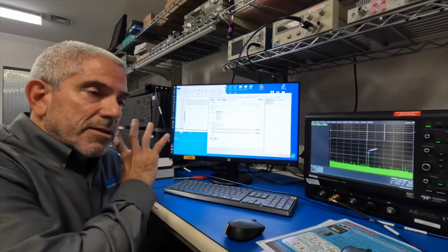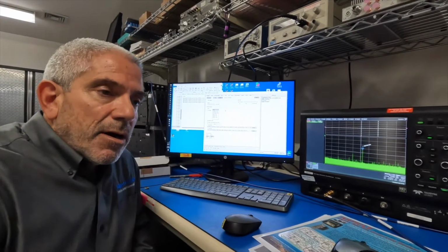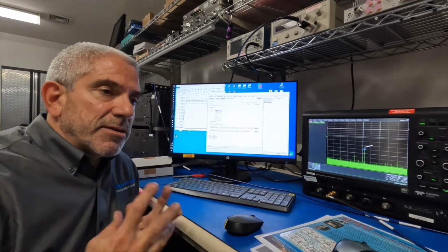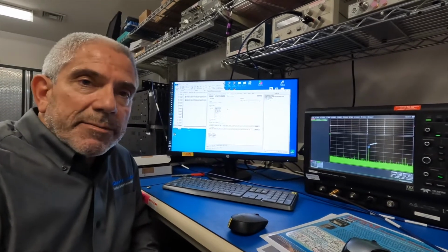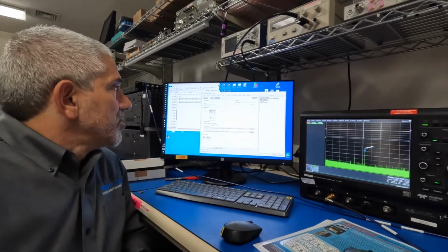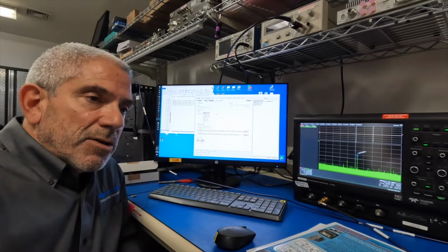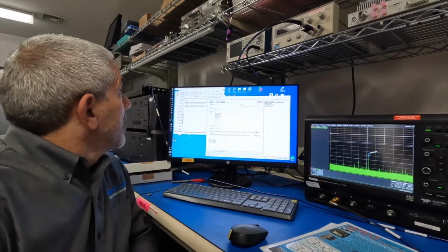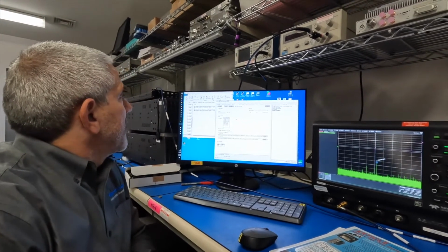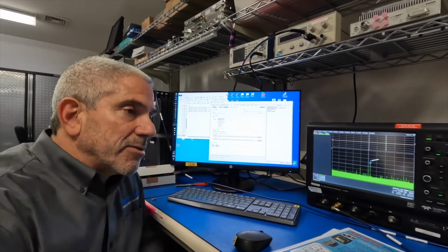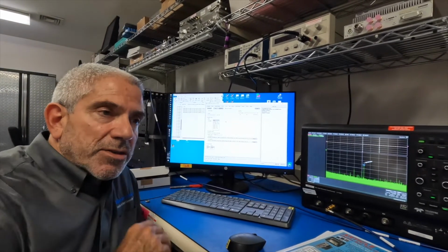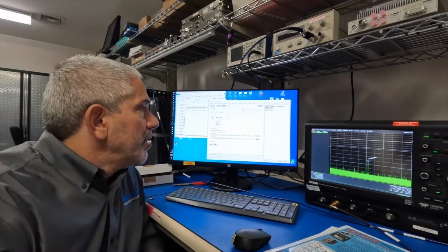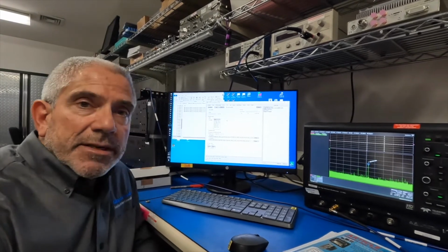So we're going to this other machine, a much more complicated RF playback and generation system for signal generation. You might have seen this in some of our other TEmS Talks videos. So what we're going to do now is play a 250 megahertz chirp with a fixed pulse width of 25 microseconds and a PRI of 100 microseconds. But we're also going to change the center frequency of that chirp from 300 megahertz up to 600 megahertz.